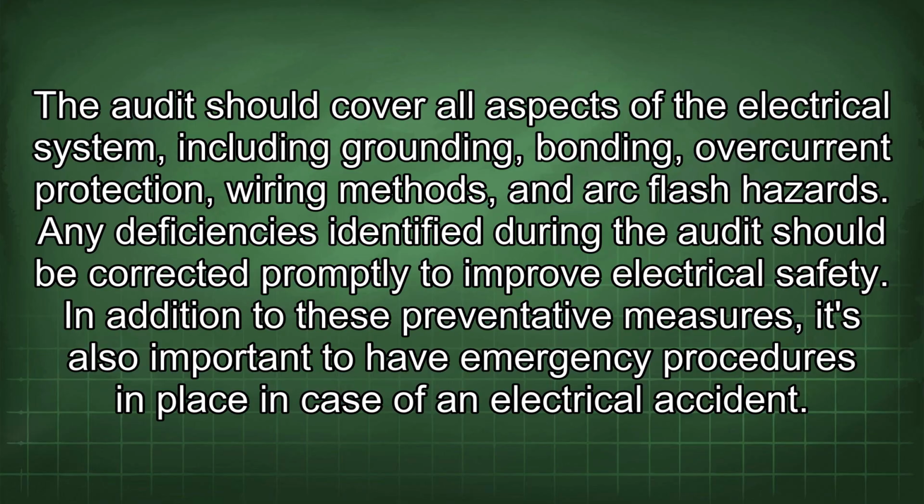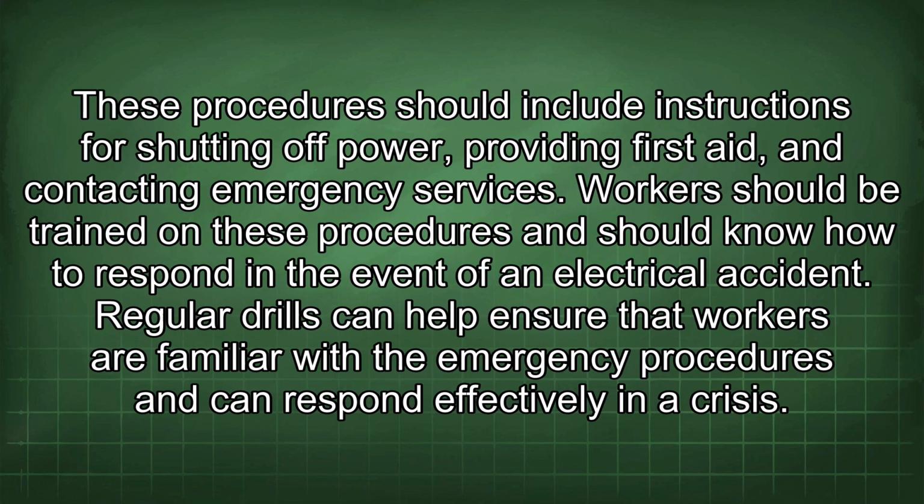In addition to these preventative measures, it's also important to have emergency procedures in place in case of an electrical accident. These procedures should include instructions for shutting off power, providing first aid, and contacting emergency services. Workers should be trained on these procedures and should know how to respond in the event of an electrical accident. Regular drills can help ensure that workers are familiar with the emergency procedures and can respond effectively in a crisis.